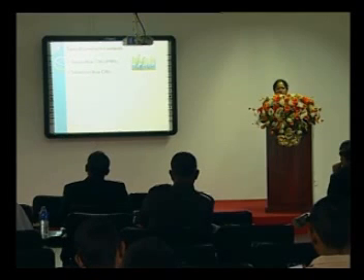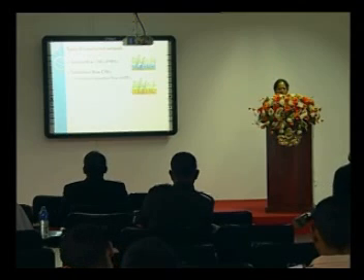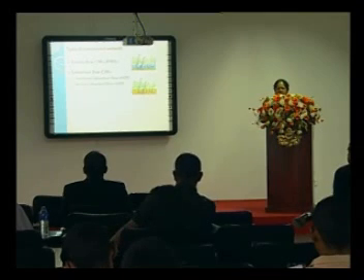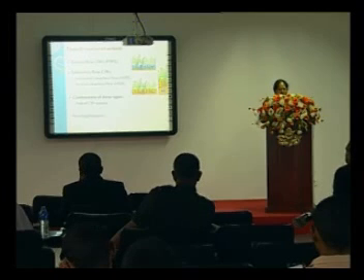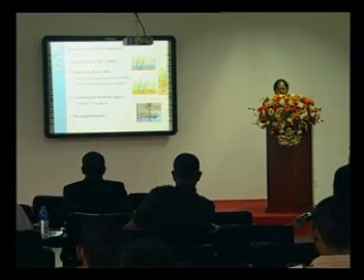According to the flow direction, we can divide them as horizontal subsurface flow constructed wetlands when the flow is horizontal, and vertical subsurface flow constructed wetlands when the flow is vertically downwards. A combination of these types is known as hybrid constructed wetlands, in which the weaknesses of each can be compromised. We also have floating wetlands. If we have a large water body, we can make use of them to treat that water.